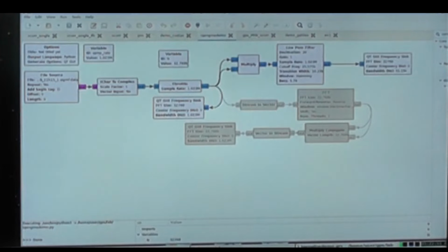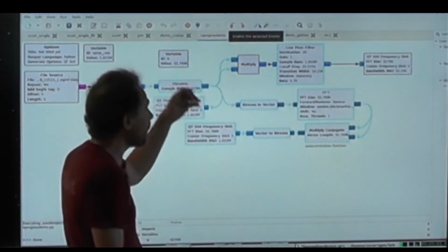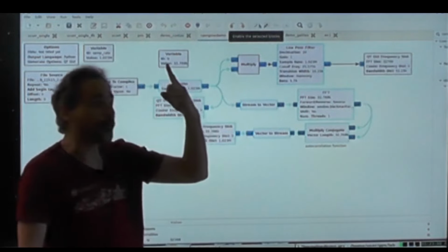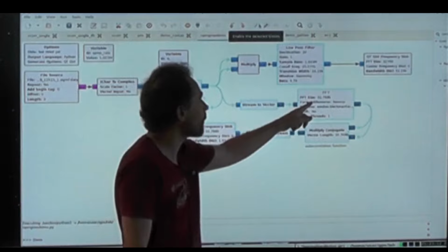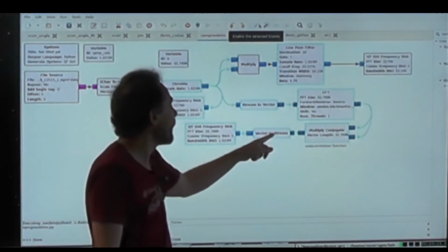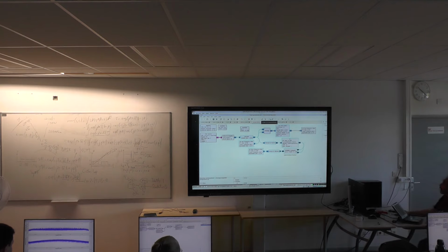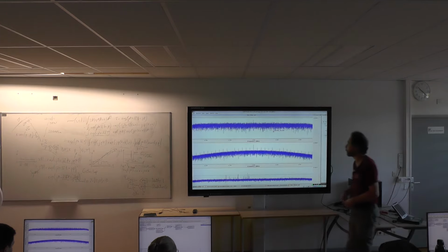And to demonstrate the concept and to really prove that we do have satellites in our recordings, how do you do the autocorrelation? Now you know perfectly. You take the Fourier transform of the incoming signal. Now we only have one Fourier transform because we multiply the conjugate by ourselves. So you take one Fourier transform, multiply by the conjugate, inverse Fourier transform, and go back to the time domain. And so now if you do the autocorrelation of a signal, what you get is a second proof that there are signals that are worth looking at.